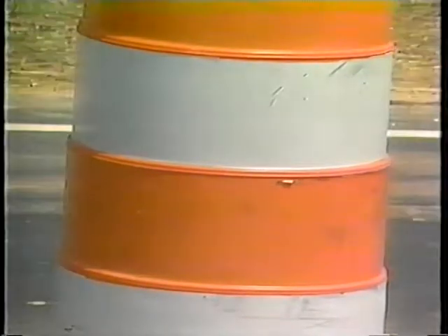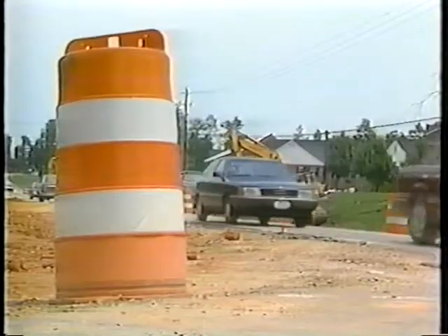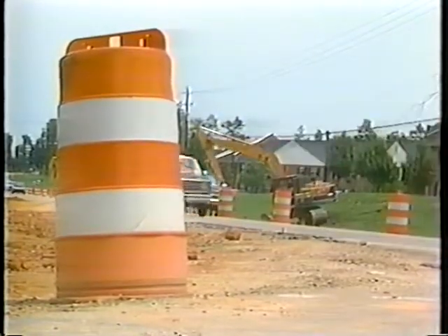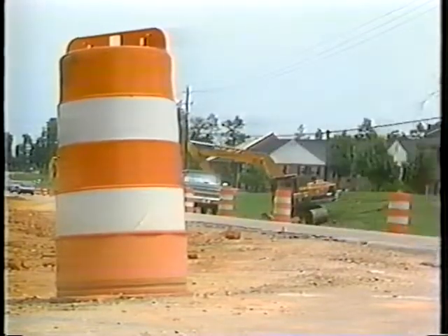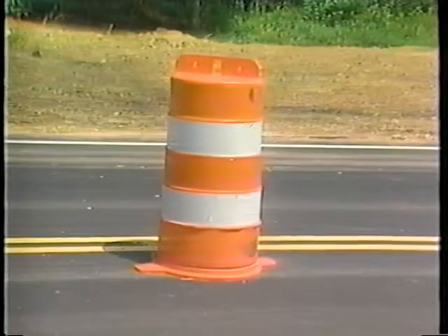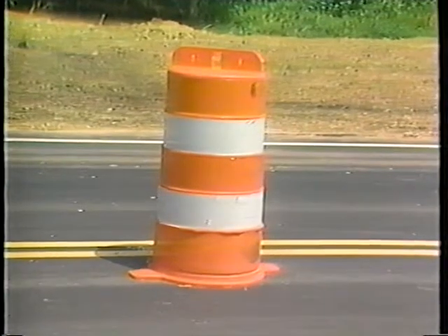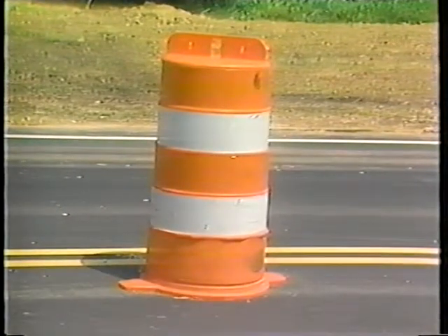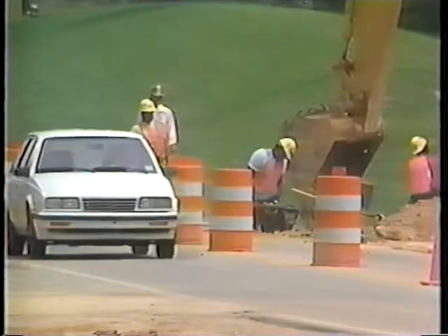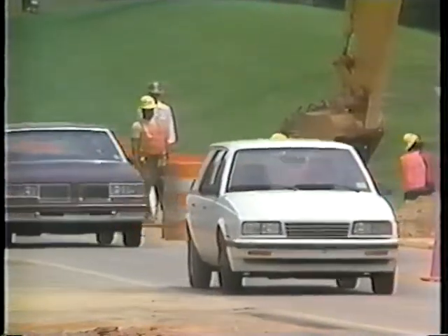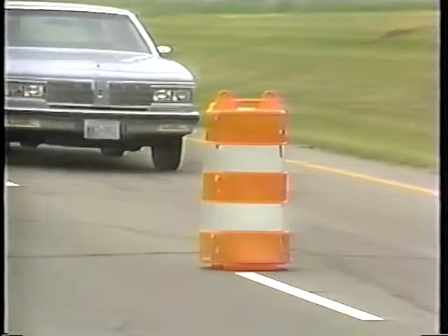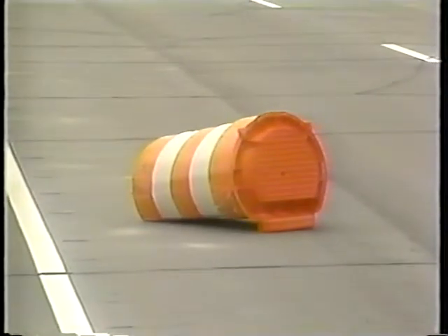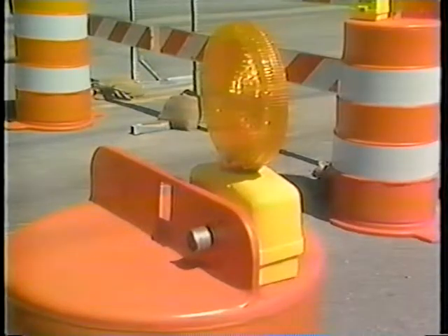The drum must have at least 2 sets of orange and white stripes, but can have non-retroreflectorized spaces up to 2 inches wide between the stripes. Drums must have a minimum width of 18 inches, regardless of orientation, and their tops shall be closed. Plastic drums can be nested, allowing for easy transport and storage. Many of the commercially available plastic drums have 1 or more flat sides to prevent rolling and have flanges or recesses for warning lights.